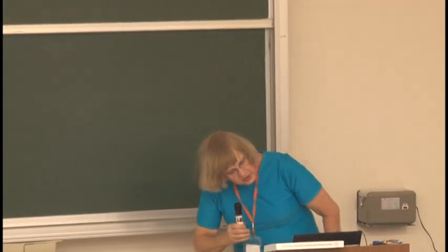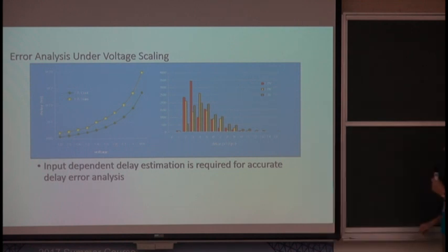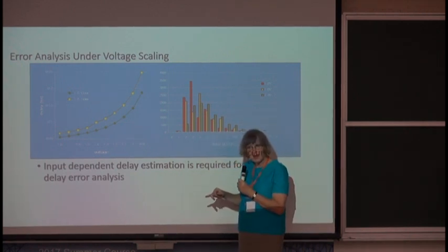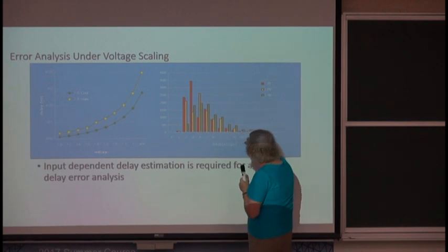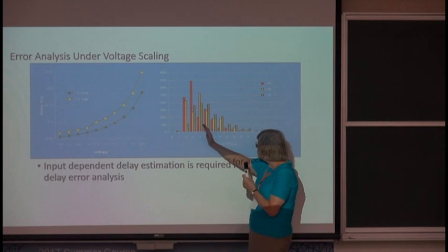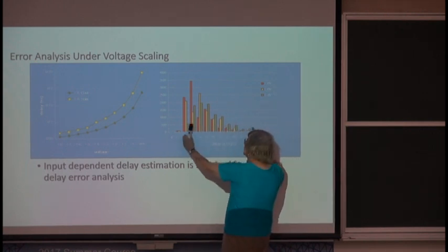If you turn down the clock frequency along that same curve, if you wait long enough, then you'll get the right answer. But you may not be willing to turn it all the way down, because remember that the delay depends upon the input values you get. As we decrease the power supply voltage, not only does the center of this bell curve move to longer delay, but it spreads out.